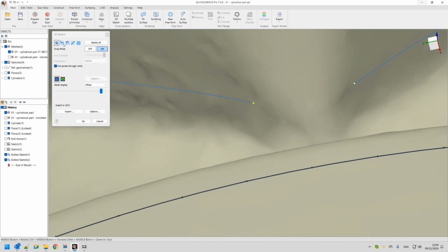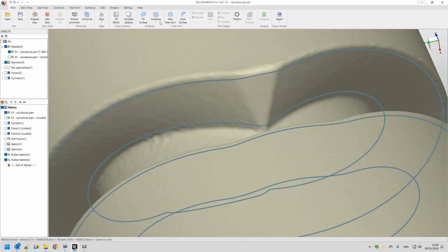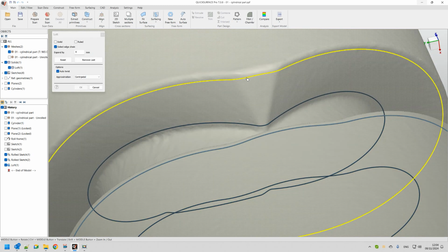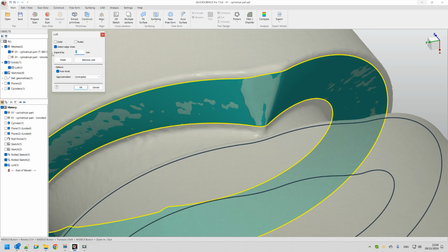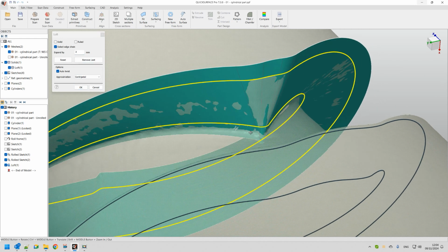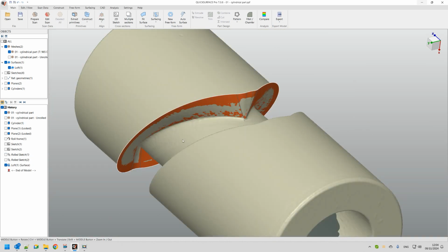Please keep in mind that you need to keep the consistency. That's by creating these, create the blend curves here, and press OK. Let's recreate again the loft shape, like this one and this one. So I click on this one and click on this, so it can create it. So this is way better and it will do the job, and I accept.